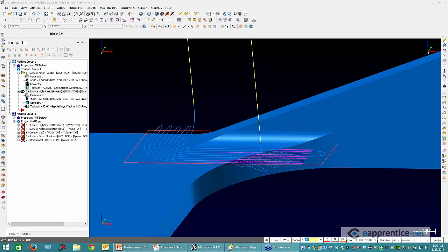Now, if you really want to get really clean, good tangential motion, you need to extend the edges of your surfaces so that Mastercam's got something that can actually be sliced by the algorithm. By extending your surface a little bit, now you've brought the edge of the tool off the edge of the surface, and you can either ignore those tangential settings or use a small value. The smaller values that you use on some of those surfaces, the cleaner the result's going to be.